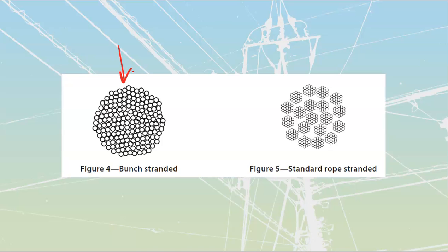We do also have rope stranding, where I'm going to have individual smaller strands that are then going to be tied together, twisted together as a rope. Usually these will once again be used for extra flexible ones. If I go with bunch stranding, I can get away with tiny conductors, which are going to be flexible, but they tend to break and to have uneven distribution on the inside. Whereas if I go with rope stranding, because I've got these things twisted into the individual, we refer to these as the lays of the rope, and then I twist them together as a stronger one, we end up being able to build off of all the cumulative strength. So it makes it much better for places that require a lot of movement back and forth.